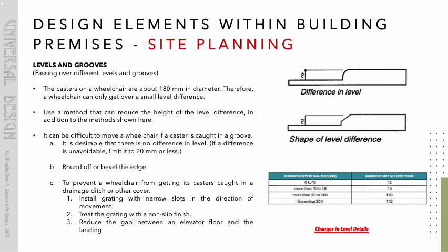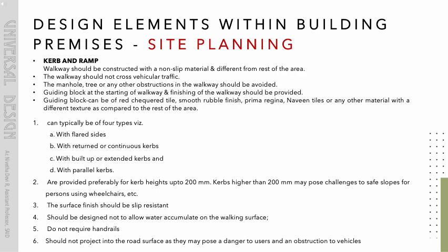To prevent a wheelchair from getting its casters caught in a drainage ditch or other cover, install grating with narrow slots in the direction of movement. Treat the grating with a non-slip finish. Reduce the gap between an elevator floor and the landing, curb and ramp.